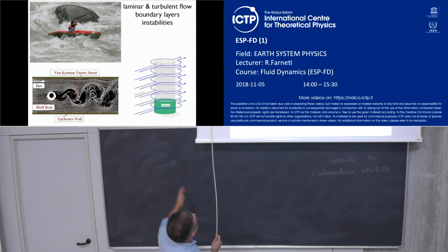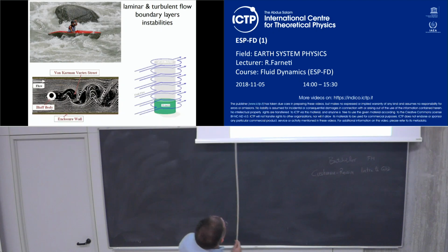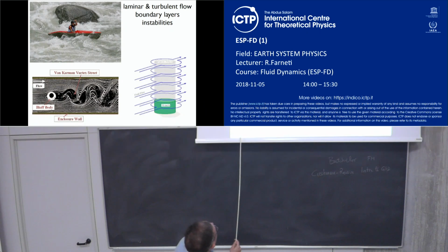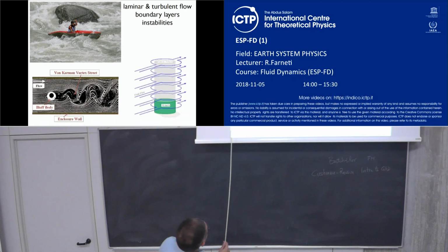And so the fluid is flowing from left to right, and starts as a laminar fluid. You see all these streamlines that we will describe in detail. All these white streamlines are describing the flow, okay? They don't tell you why the flow is going the way it is going, but they describe the flow. So this flow is laminar, so all these streamlines have the same property in space, and then after hitting the object, you see that there are some strange patterns arising.